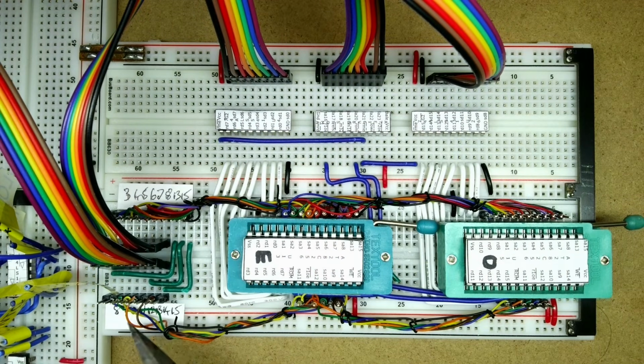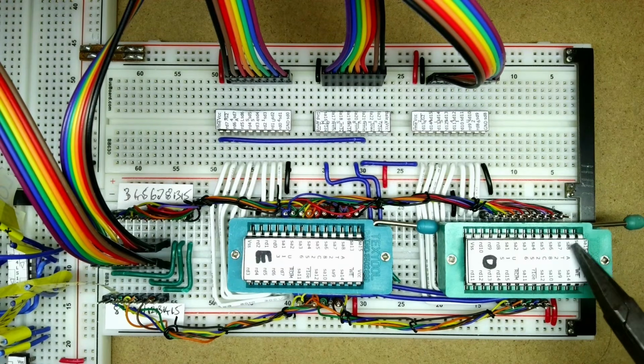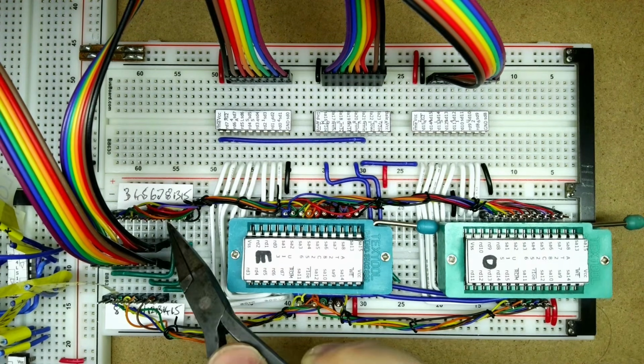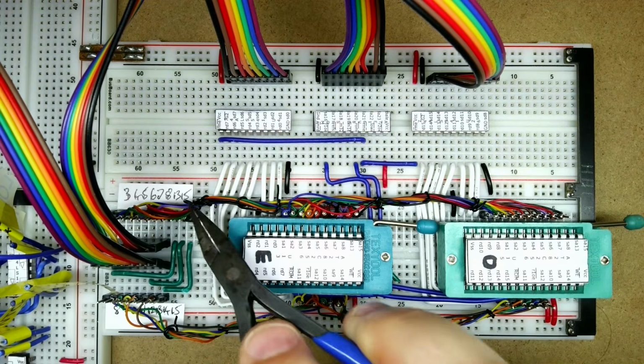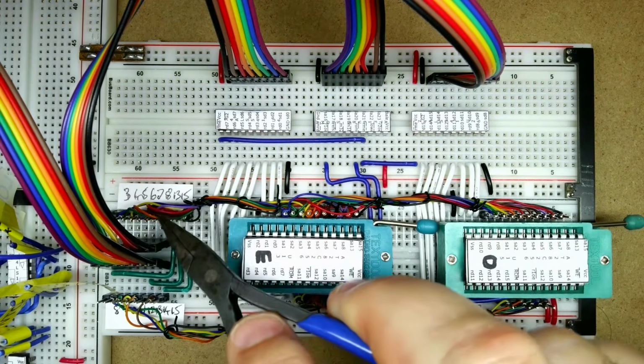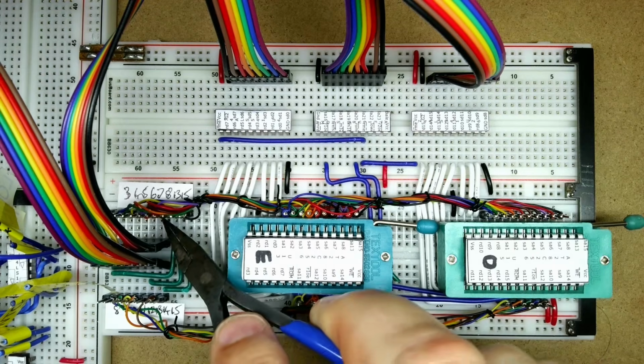Okay, so I've made up these wire wrap connectors. On this side, we've got all of the address pins: SA14, SA9, SA10, SA12 and SA11, all wired between the two chips here and then wired down to the appropriate pins down here. And on the other side, you've got SA15, SA13 and SA8 wired down to here and then to here, and they come round to this other side over here. So you've got 8 to 15 here and 0 up to 7 there, and then our 8, 13 and 15 are these last three at the end here.